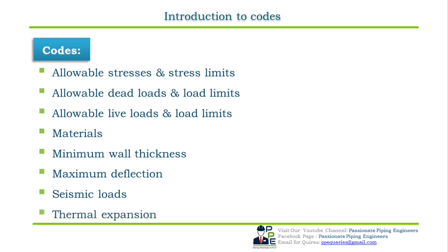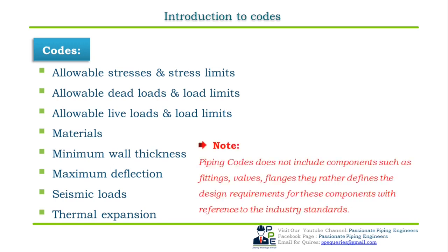As we know, metals expand when heated and contract when the heat is removed. That means it is directly proportional to temperature change. Similarly, all the pipes and vessels expand due to the temperature of the fluid flowing through them or from the surrounding environmental ambient temperature.